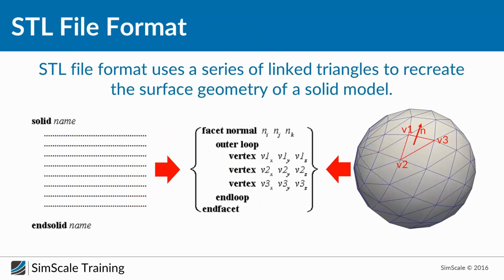So here it's really important because during this workshop you will work with STL files and you will edit the STL file. So I think it's really important to understand how the file is built inside and how the geometry itself is built. Like I told you, the geometry is built based on many elements, and every element is represented by three vertices in space.